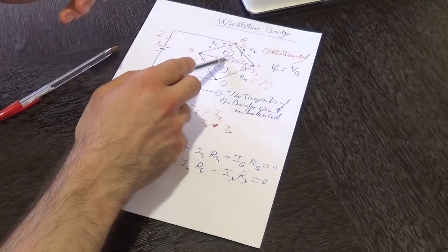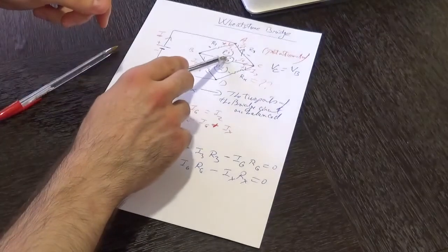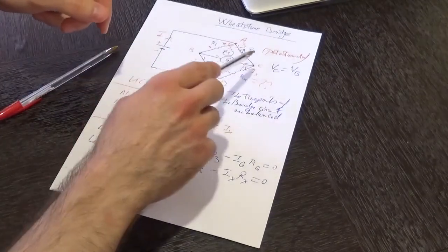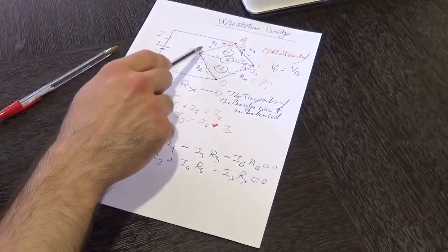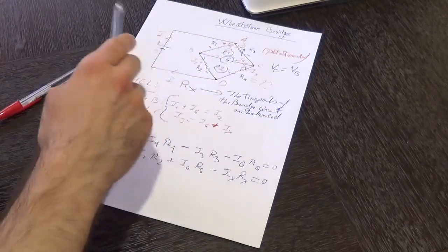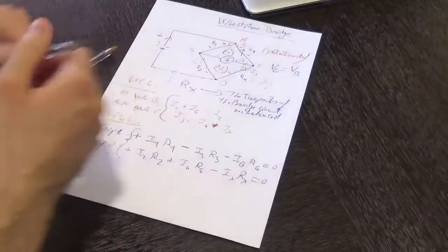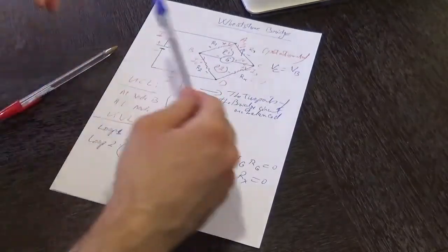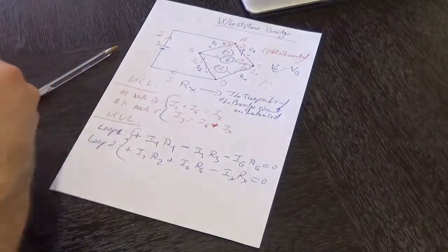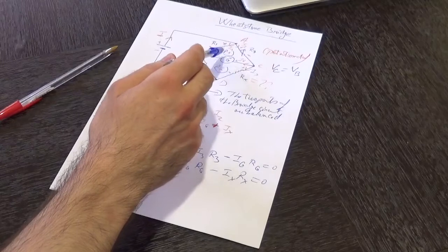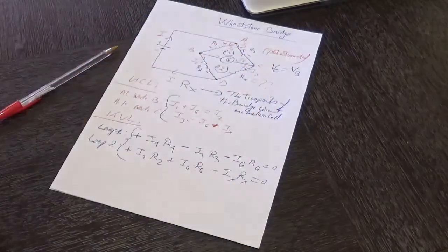In that case, once you obtain 0 volts on the galvanometer, that would imply that the potential at that node is equal to the potential at node B. Therefore, these two bridges are balanced, and the potential difference between them is equal to 0. So the key point over here is to keep varying the resistance of that potentiometer until the galvanometer is reading a potential difference of 0 between these two bridges.